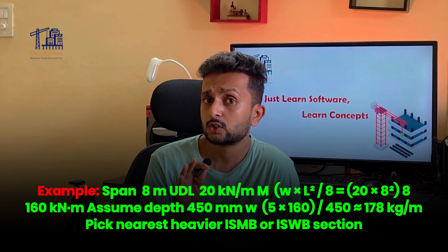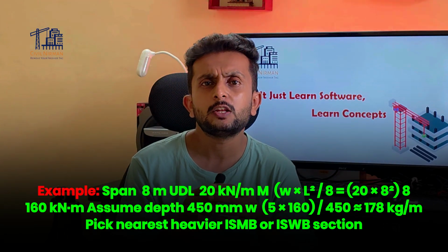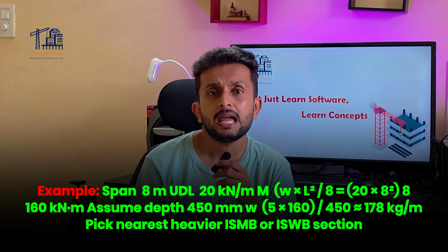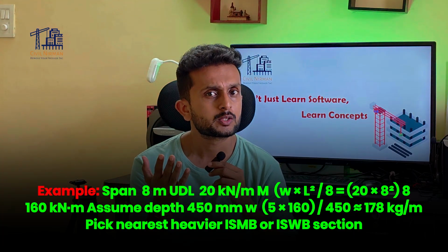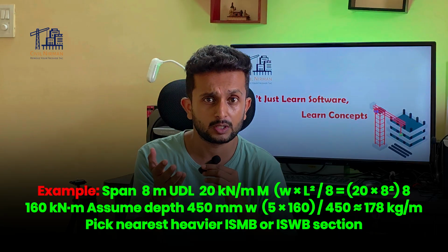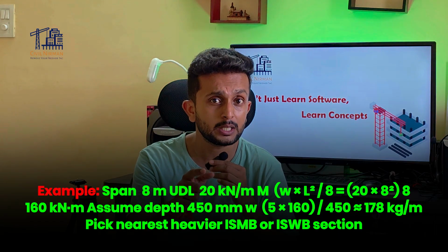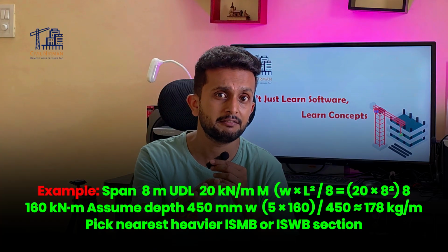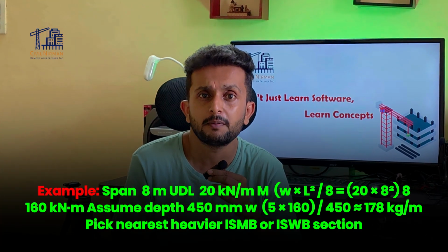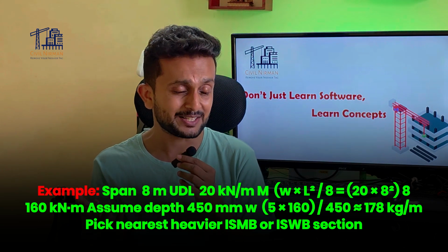So let's understand this through an example. Let's say you have a span of 8 meter, UDL value of 20 kN per meter. M you can figure out using WL square by 8, which gives 160 kN·m. We assume the depth to be 450 mm, and based on the following equation, if you put the values you will get the weight as 178 kg per meter. So you can pick the nearest heavier ISMB or ISWB section.